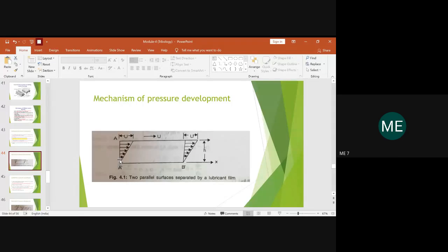But as the layer of the fluid film will be moving, the pressure gradient also will be different. We have studied the pressure gradient distribution previously. Here also it is the same, the velocity with which the fluid flows will be slightly increased. Here it will be 0, slightly you will get some velocity value here. Here it will be still higher, still higher, and here the velocity will be constant enough. This is what we have assumed at a condition where no slip is happening.